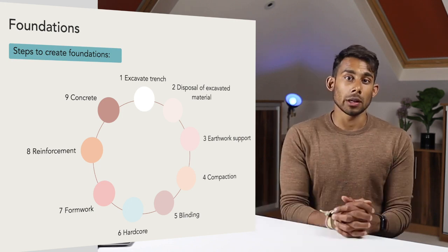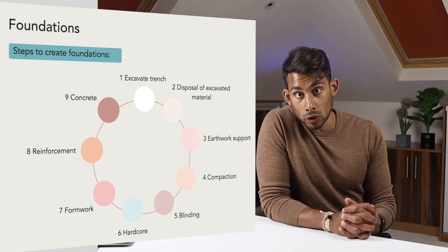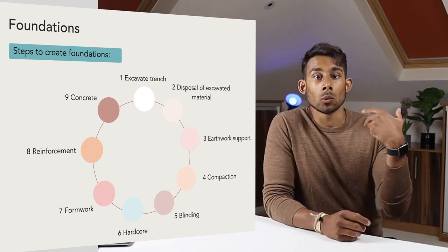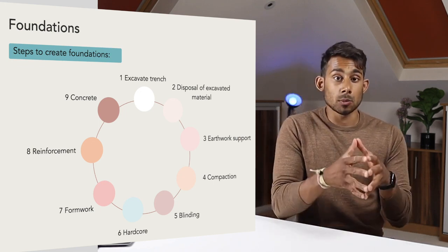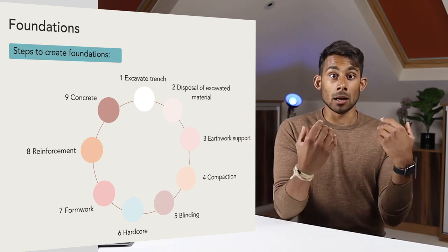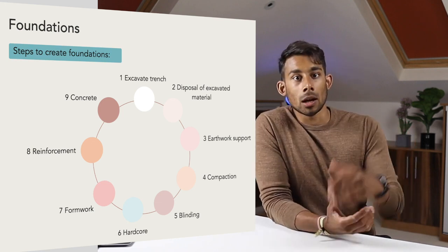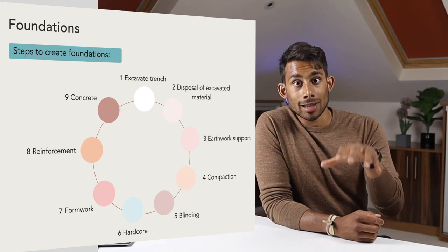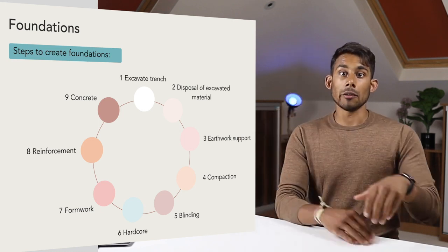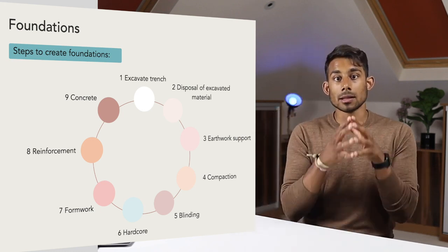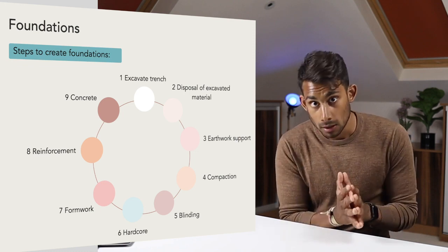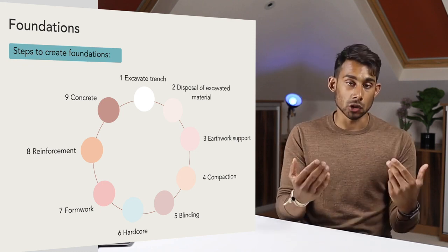You could pour concrete in the rain as long as the ground drains well and there aren't any rainwater pools. Once it is poured, cover using a tarpaulin or sheeting while it cures. Heavy rain will damage the surface of the concrete, so if appearance is important, make sure there is a cover to keep the rain away until you are happy to apply the final finish.